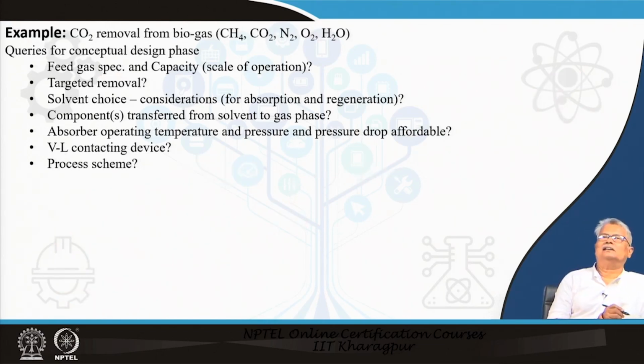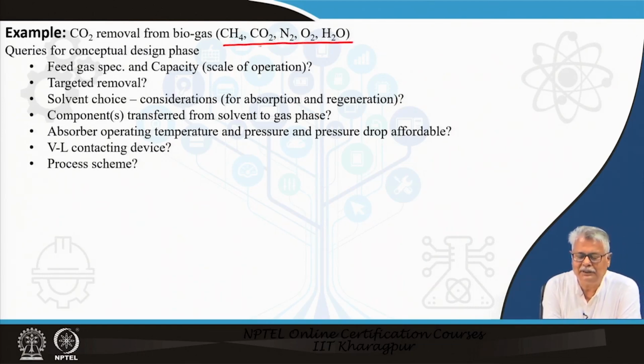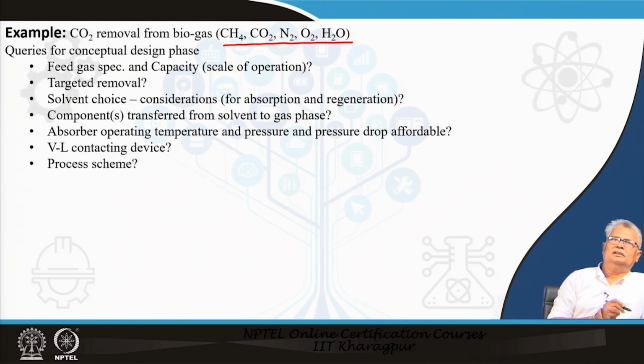We have here another example with us. It is basically the CO2 removal from biogas. In fact, if you have a biogas production, normally the gas that you will be producing will be a mixture of a good amount of methane, fair amount of CO2, small amount of nitrogen, oxygen, and it will be moist. If we try to handle this and we think of removing the CO2 part of it primarily, we have to face the same questions, and we go for the conceptual design by following the steps.